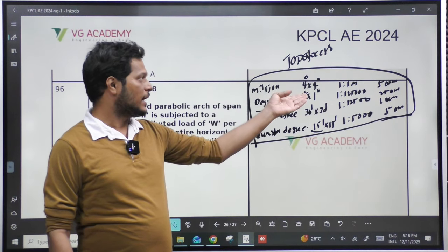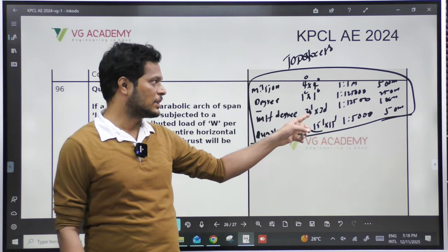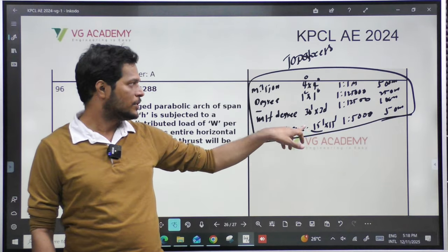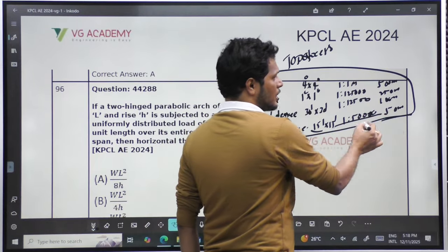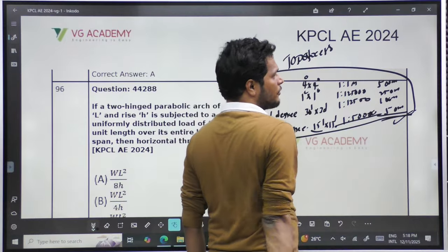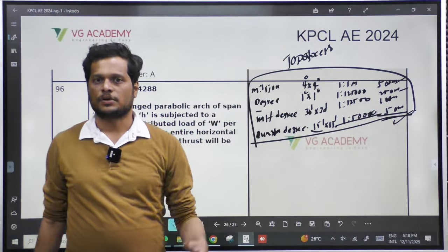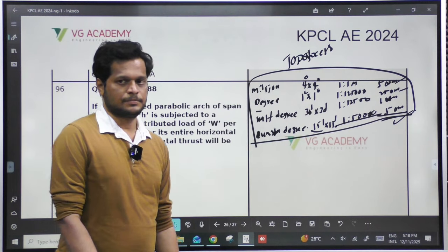Okay, this is again divided into 4 parts, which means 2 by 2, so 30 minutes. Again this is divided into 4 parts, that is 15 by 15. So this scale is 1:50,000 and the contour interval shown is 50 meters. So this is 100, 500, 250. Okay, so this is the standard followed by Survey of India for publishing maps.